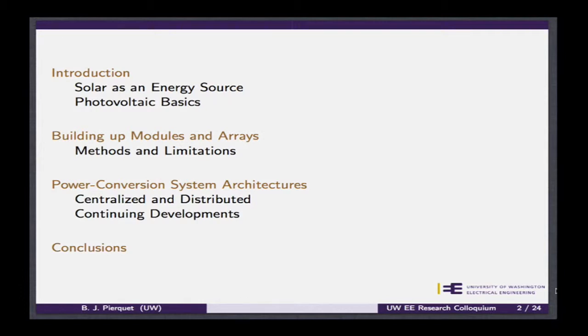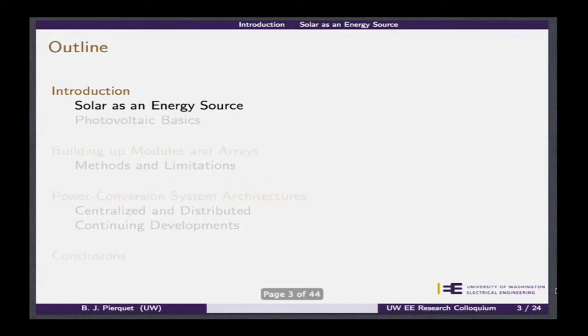And then we'll go into a bit into the conversion architectures in terms of the system level. How do you distribute the modules amongst different inverters if it's grid connected? And at what level do you put these converters, whether they're going to be located with individual processing, or going to be aggregated with a single centralized version, and then we'll just do some quick conclusions.